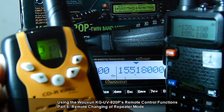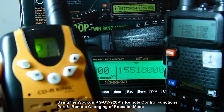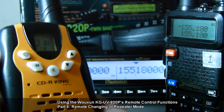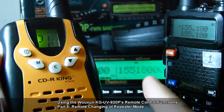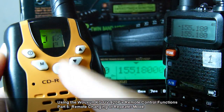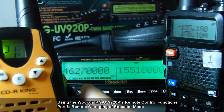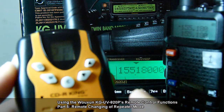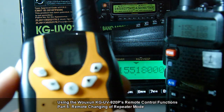Now let's check it if it's really in normal communication mode. We try to transmit. As you can see, it's not receiving. The other side, the VHF radio is not receiving. TX transmitting, not receiving. So we are in normal communication mode.